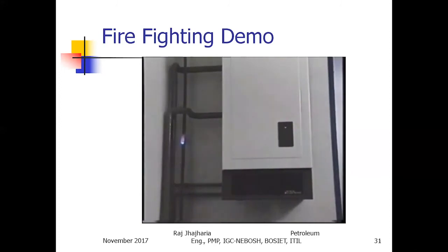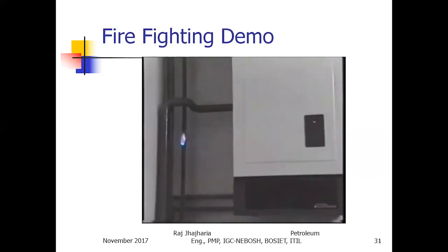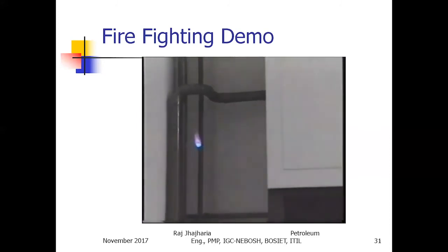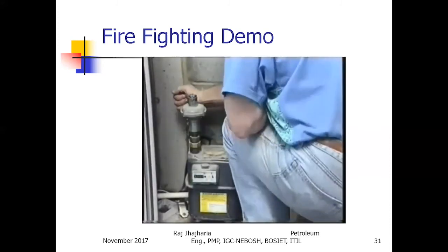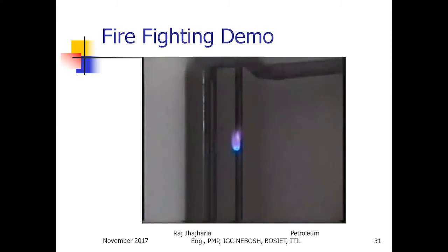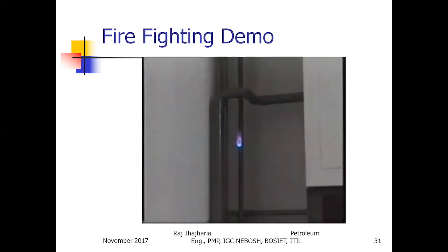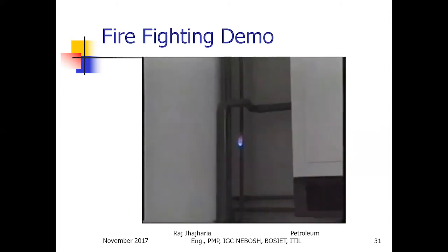With fires involving gas, there's a danger of explosion, and they should not be fought with an extinguisher unless you've received specialist training. In most instances, if you can, shut off the gas supply, but do not extinguish the flames before doing so, as the escaping gas will build up and is liable to explode.